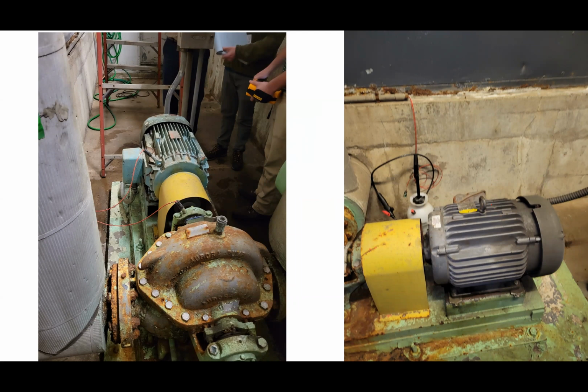Any ideas? Pump, right? Yeah. A centrifugal pump is what that is. And so it's pushing water. This is actually specifically inside of what I call an air washer. This is an old textile mill, right? And what they're doing here is they're pushing air through the building. And this guy is pumping water through a set of coils that are going to cool it off. All right. And so this is a typical operation of what I have.